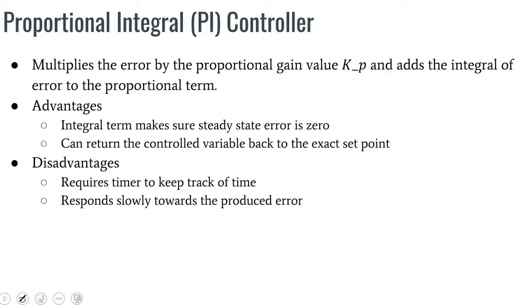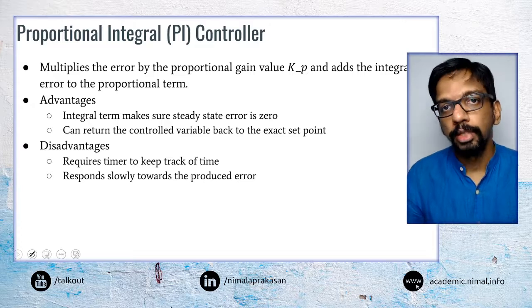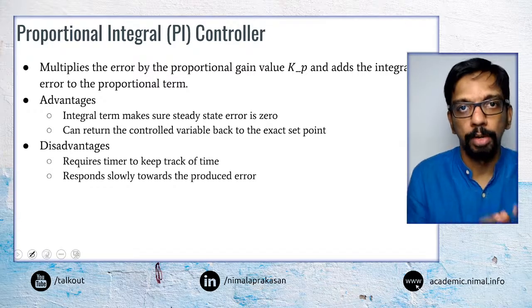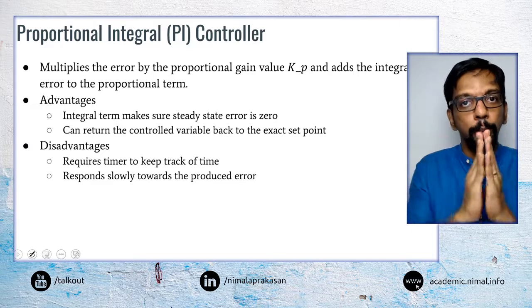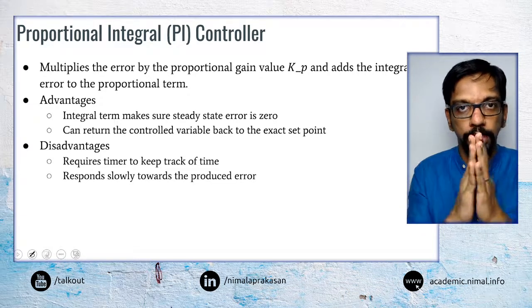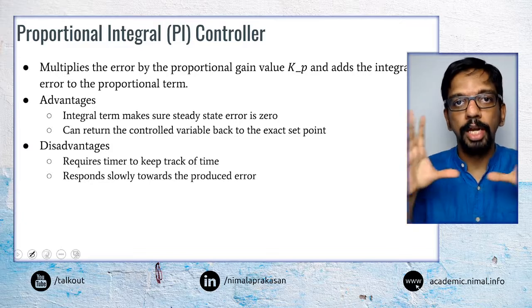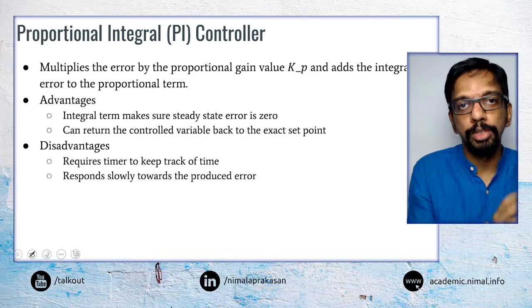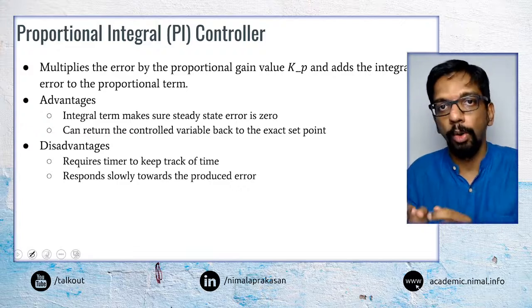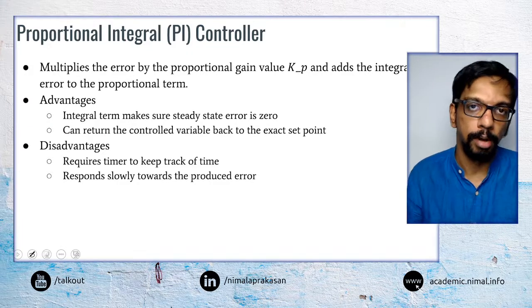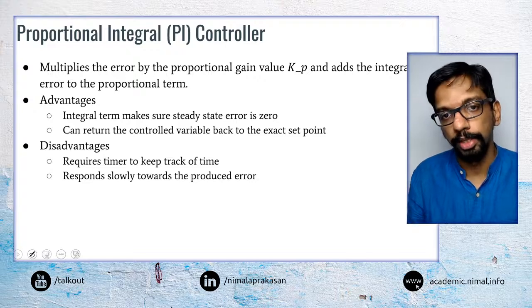But the reality is the proportional control is still the useful one, because the proportional control will give you the largest difference that you need to work particularly. So if the difference is larger, it will give the largest effect at the beginning itself. So you would always use the proportional control. You will not use only the integral part. You will always use the proportional and maybe the integral part or the derivative part along with that.